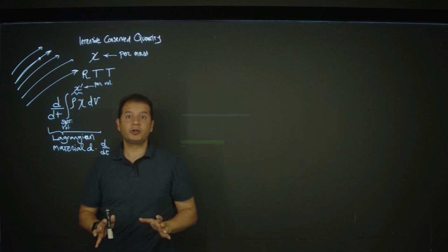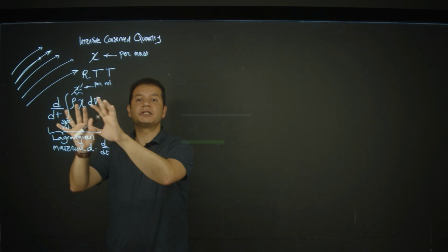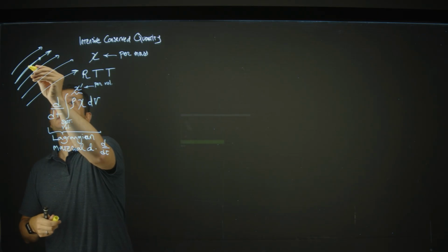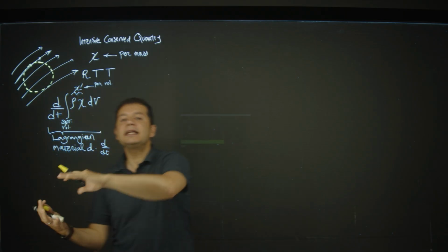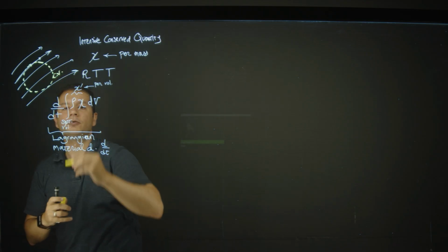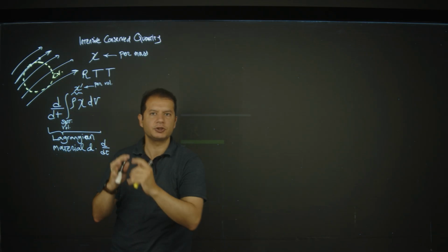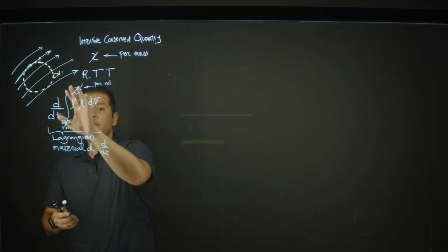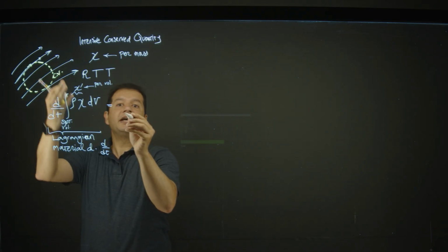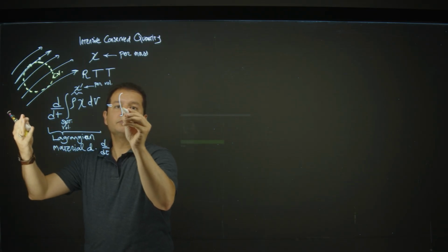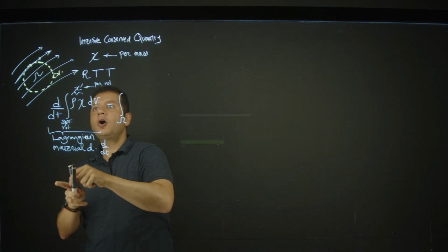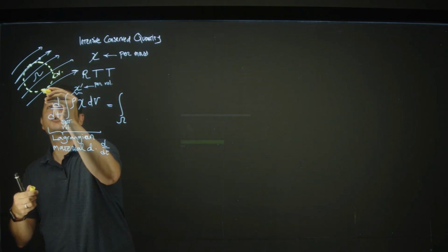There is another perspective in fluid mechanics that observes the stream of flow from outside, from a fixed point. So you fix your observation and let the flow happen while you stay fixed in your position, your control volume, a fixed location. Now, this will be equal to the change of the amount of X in your control volume, so that will be over the volume of the control volume, let's call it omega, and I call the boundary of the control volume partial omega.